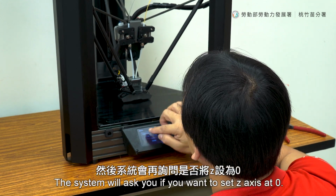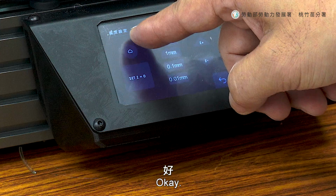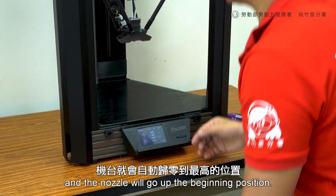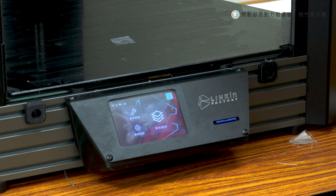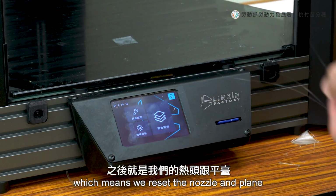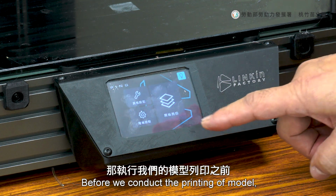The system will ask you if you want to set z-axis at 0. Press yes. Okay, now it's done. Press the home base icon to reset to 0 and the nozzle will go up to the high position. We just completed the calibration for height of the 3D printer now, which means we set the nozzle and plane with A4 paper.